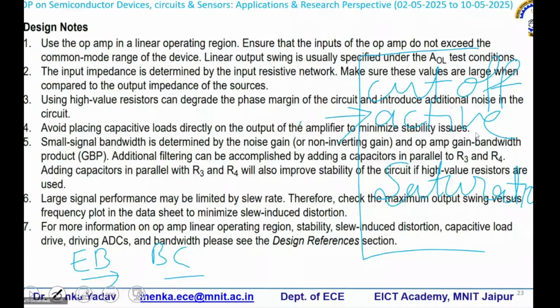This is the forward bias and that's the reverse bias. And if it is a MOSFET, then I will ensure that my current I is given by this formula, I = (1/2) mu_n Cox W/L (VGS - VTH)^2 (1 + lambda VDS).